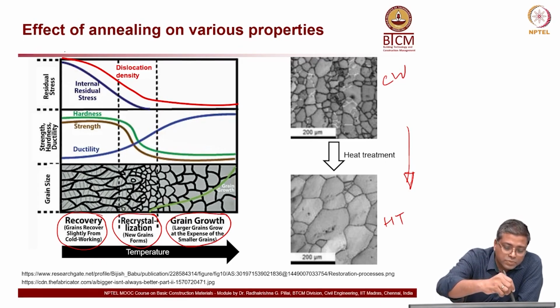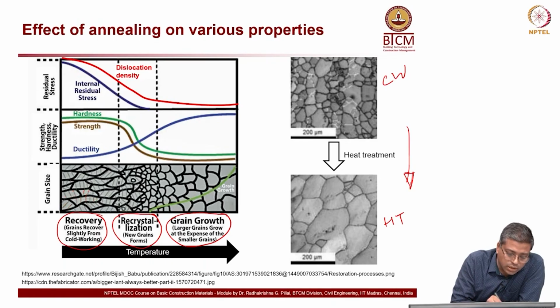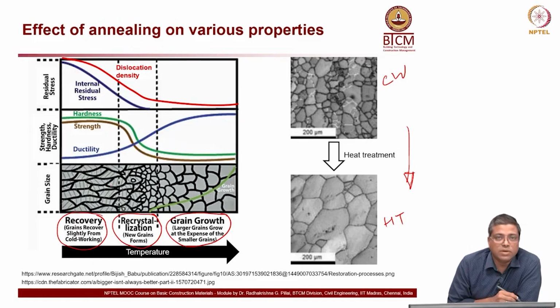Here, look at the dislocation density. The first thing to look at is the light gray lines, which are the dislocations present in the material. Then you have these dark lines, which indicate the grain boundaries. You can see several grains there.